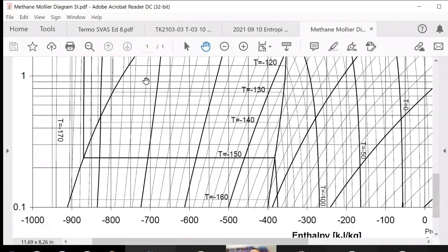So we know the delta. And then when we have a certain point here, we measure the delta of the enthalpy. Minus 700 compared to minus 750. So this is 50 divided by the total, maybe around 400. So the mass fraction is 50 divided by 400, things like that. This is the way to measure how much liquid and how much vapor.